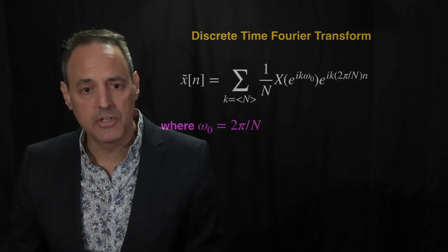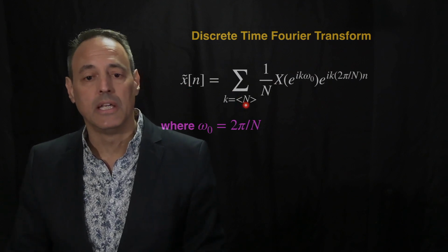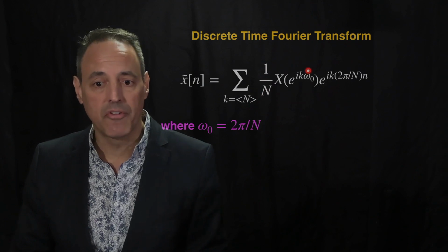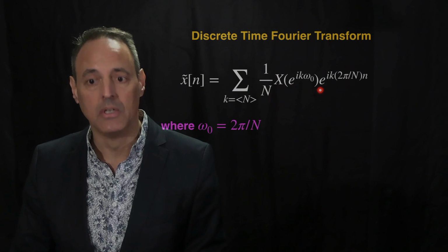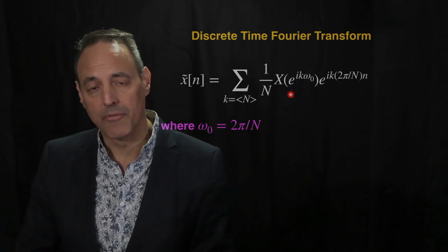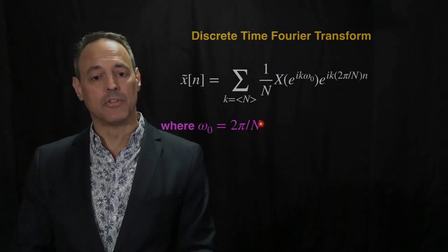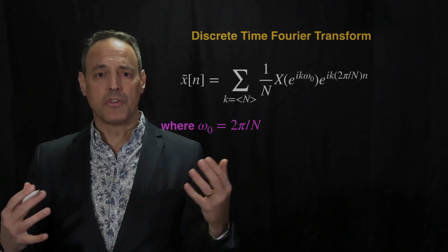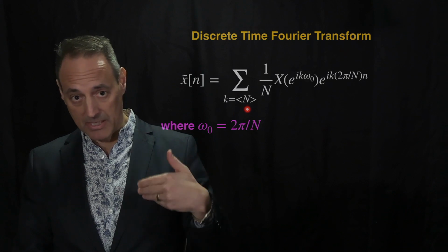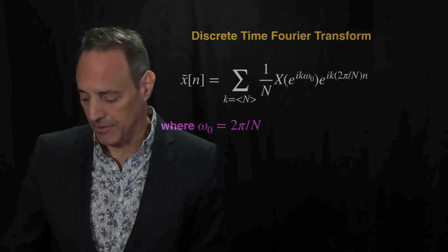So if we look now at the representation of our signal x tilde, this is the approximation to the full signal: the finite sum over a finite number of n. Remember, n is the number of period points. 1 over n times this coefficient that we compute, which is again the sum over that signal times each of the Fourier components. So essentially this is a normalized version of the Fourier coefficient A of k, where 1 over n is taken out. And here remember that omega naught is 2 pi over n, so this is your fundamental frequency. Once you've moved into the discrete time case, we have to take into account the fact that we're no longer integrating or summing from negative infinity to infinity. We're summing over a finite number of n in an interval. And so we have it right here in this representation.